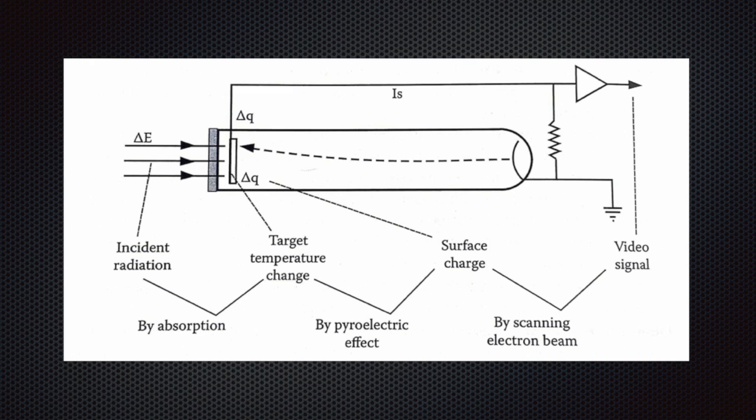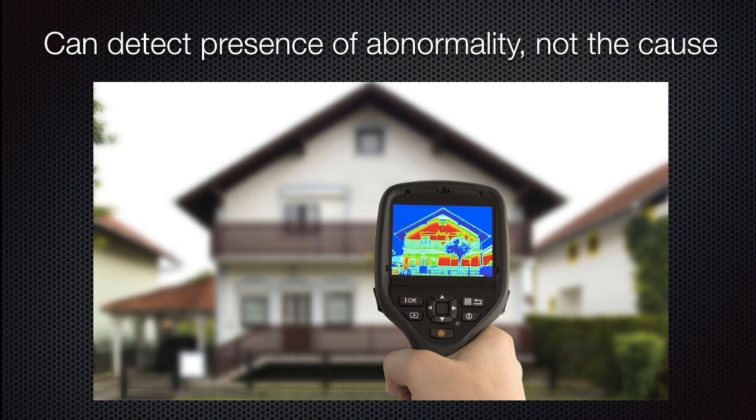Since the emissivity values are known and constant, it is possible to use the corresponding curve to calibrate for temperature and measure other objects without knowing their precise emissivity values, and finding their temperature relative to that of the black body object. Despite its wide range of applications, there are a few notable limitations of infrared thermography. From the broadest standpoint, infrared cameras can help detect abnormalities in the thermal distribution of an object, but they cannot directly identify the cause of this abnormality. In many cases, determining the cause of a potential issue detected using infrared thermography involves the use of either intuition or pairing this technology with another technique, such as vibration analysis, oil analysis, or ultrasonic inspections.